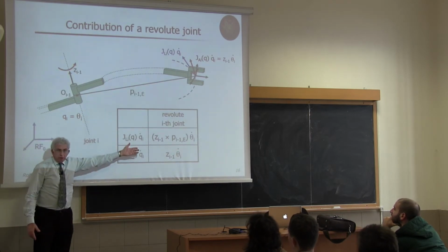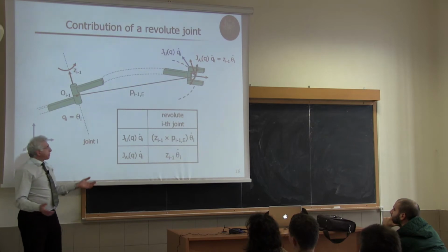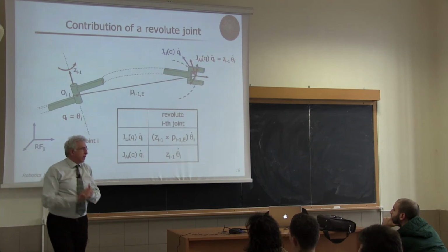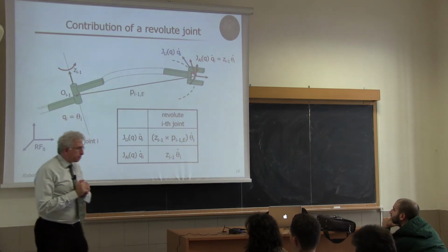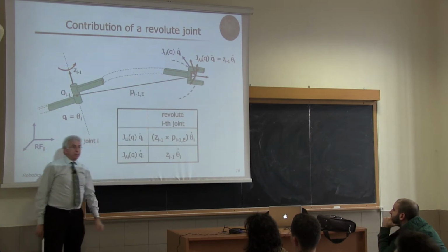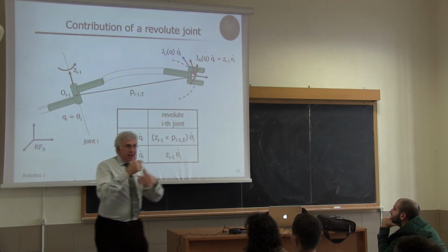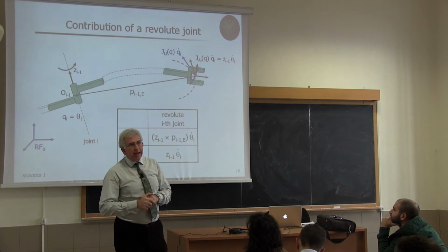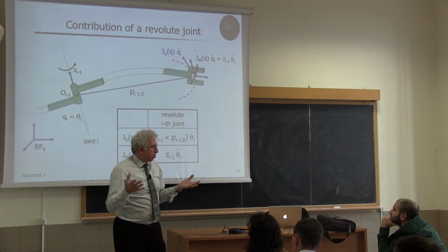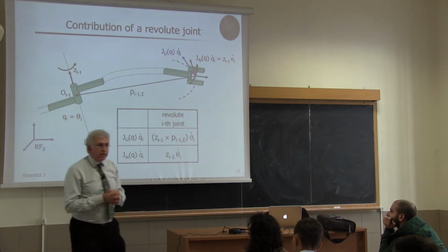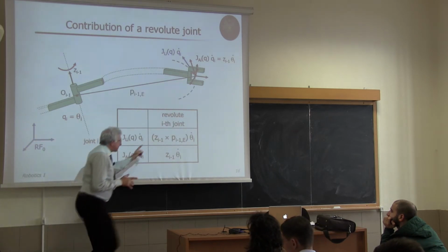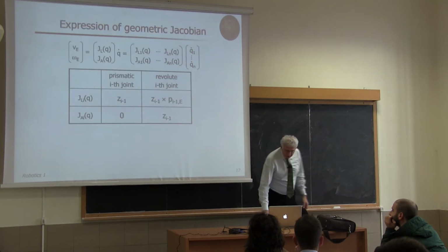So when you have a vector product, the result will be always the same if you change the point. Any point along this joint axis will provide you the same result. Okay? So why am I choosing this pi minus 1e? Because this vector can be computed as a side results of the direct kinematics, because it goes from one origin to another origin. So it's included in the Denavit-Hartenberg transformation matrices. Okay? So pay attention to this. So this is the efficient way.